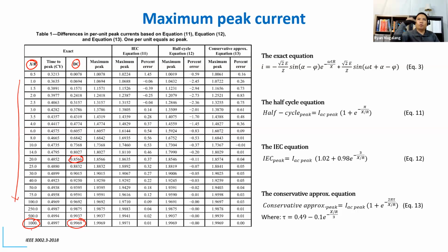So the more you go to the higher voltages, to transmission, high voltage, extra high voltage, the X/R ratio tends to go higher. Going to the lower voltages, because you have more resistive parts now, you have a lot of cables, that brings down your X/R value.